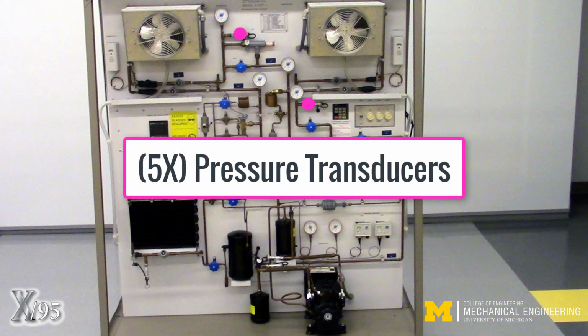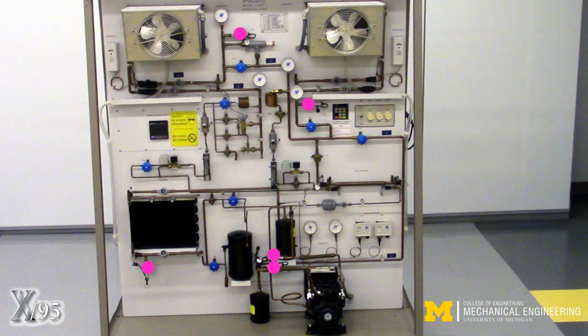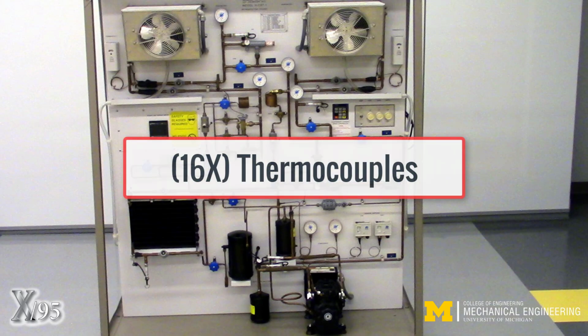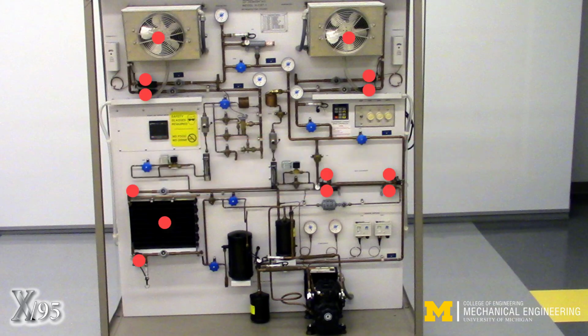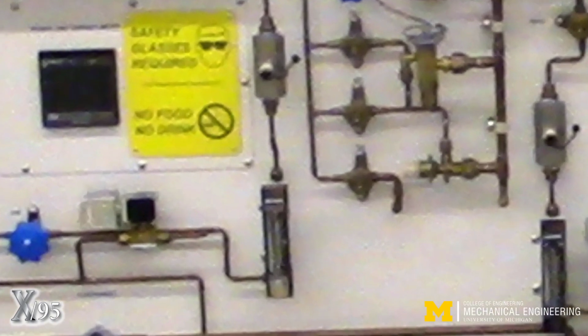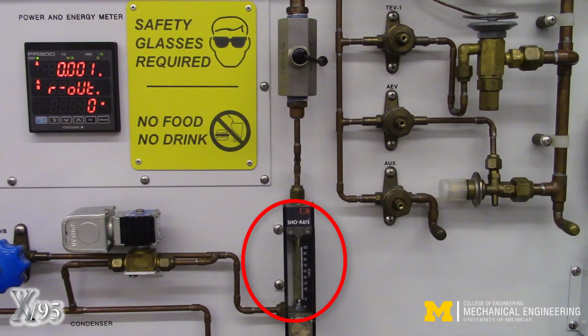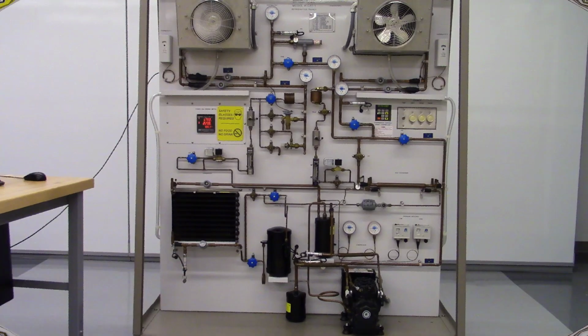The cart is instrumented with 5 pressure transducers and 16 thermocouples to measure pressure and temperature throughout the circuit. Additionally, a sight glass and electronic flow meter measure the freon flow. Be careful, the latter is only accurate when the refrigerant is a saturated liquid. At first, the cart can be overwhelming.